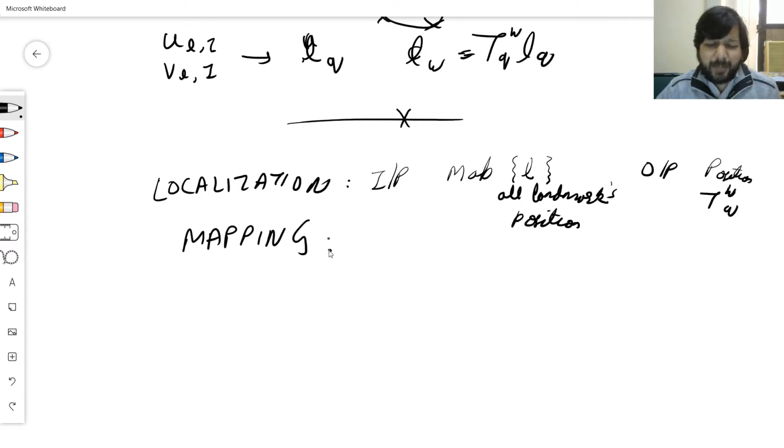Now let's come to mapping. What did I do? I looked at the landmark. I knew exactly where I was when looking at that landmark. So the window corner, the door corner in case of an image, or in case of a LiDAR image, the actual corner, or sometimes the entire LiDAR image. I know exactly what I am looking at in my coordinate frame of reference. With stereo, I could do the depth calculation and transform it into my coordinate frame of reference. In LiDAR, of course, it gives you d alpha cos alpha, d alpha sin alpha, the position.